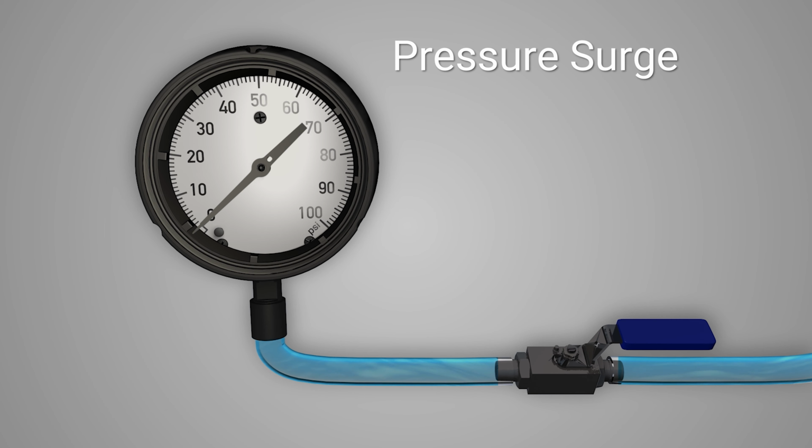The design pressure is the maximum pressure that your gauge will experience during your application at a given moment in time. There can be a surge of pressure when the machine turns on, or surges or pressure spikes can happen at other times. Pressure gauges can handle 130 to 150% of the range, depending on the gauge. But if the pressure goes beyond that, you will need to get a gauge with a higher range or protect the gauge from possible overpressure.